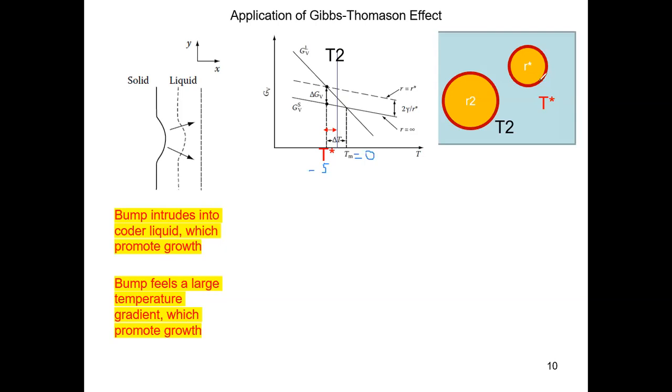In this case, I impose a delta T of 5 degrees, because my temperature is 5 degrees lower than my Tm, so I basically induce 5 degrees of supercooling in the system. This is my delta T, or I call it delta T naught, equals 5. I didn't write the unit, but this is 5 degrees Celsius. So that's basically the general setup.